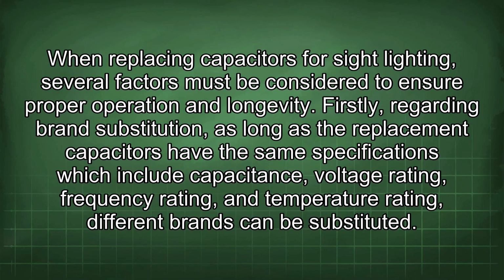When replacing capacitors for site lighting, several factors must be considered to ensure proper operation and longevity. Firstly, regarding brand substitution, as long as the replacement capacitors have the same specifications, which include capacitance, voltage rating, frequency rating, and temperature rating, different brands can be substituted.